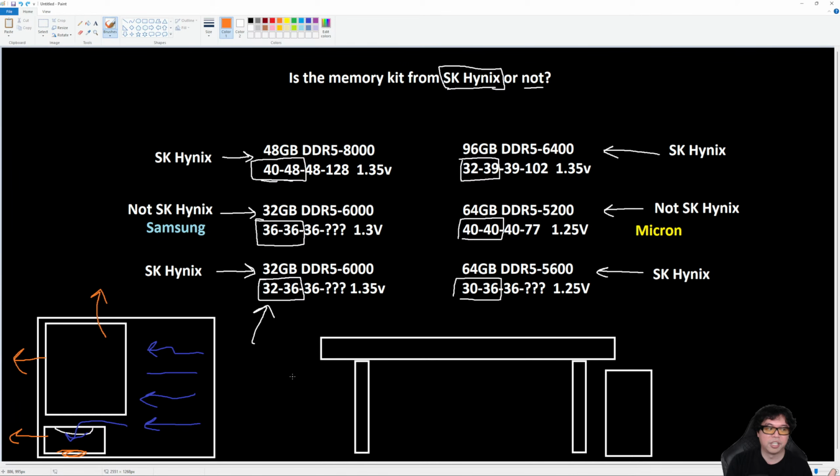And also, the big difference is that for an aquarium case to get equivalent airflow to a standard, well-optimized traditional case, you need to use way more fans. Way more fans, which means way more vibration and noise. And even with all those extra fans, there's still turbulence in certain parts. There are pockets of air that get caught and don't circulate enough, and they tend to heat up when the computer's under load.